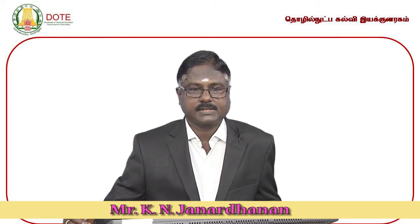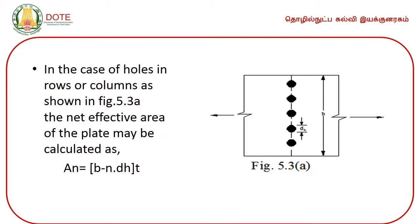And in the previous class we have seen the design of a tensile member, when it is subjected to rupture, or the failure takes place in the net cross-sectional area. For example, if a plate is subjected to tensile force, how do we calculate the net area of the plate which is having a row of holes? This is an example, of course an illustration, and these are all the application of tensile forces.